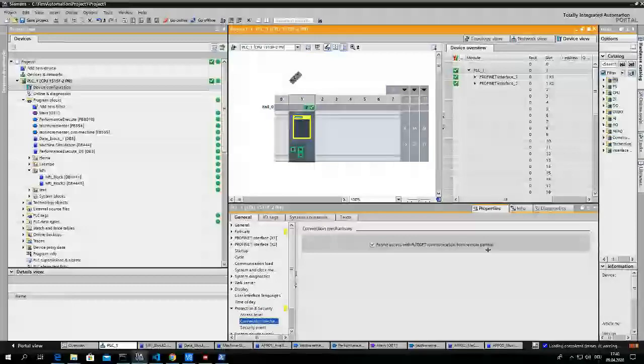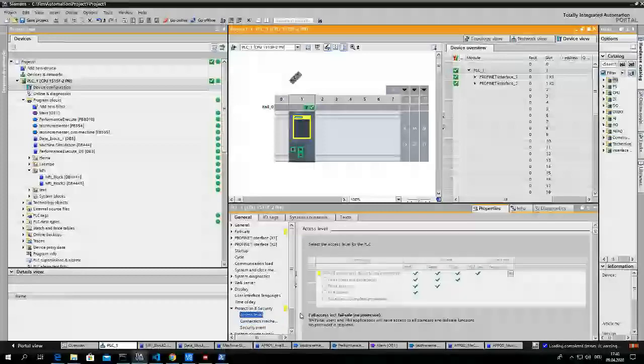The first thing that is quite important is the connection mechanism of the S7, which is set to this one. This is the put-get communication. It is usually used to communicate with some HMI system so the machine users can interact with the machine. This is also important for us to communicate with the S7. So this is the very first important thing to activate when we want to communicate via PLC4X with an S7. The next one is to give full access, but this is usually activated when machines are communicating with an HMI. So this is the most important part of the basic configuration of the S7.